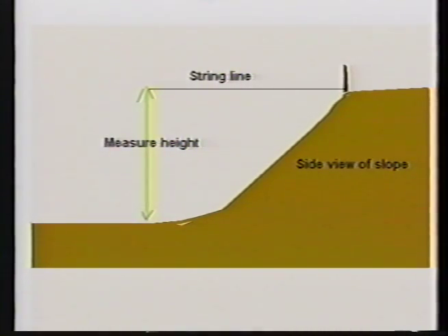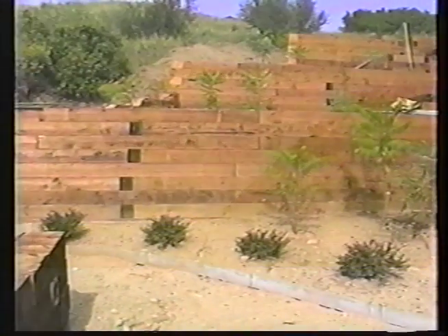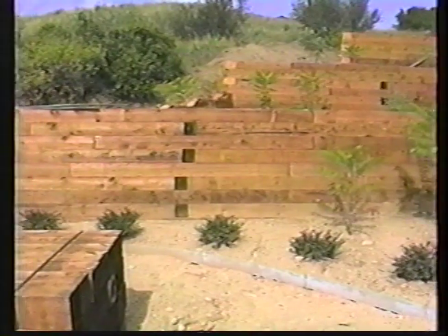Next, determine the elevation of the wall. This is done by first installing a wood stake at the height you want the top of the wall to be. Attach a string line to the base of the stake and extend the string to the level where you want the base of the wall. Then, hold the string level and measure the distance from the ground to the string. Do this in several places along the trace of the wall to determine the average height of the wall.